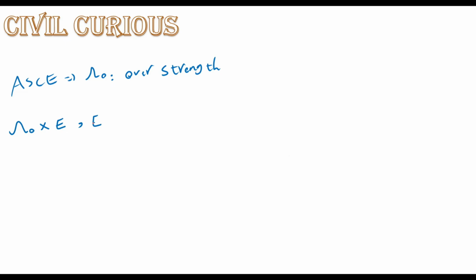Those earthquake loads include earthquake load in the x direction, positive and negative. Also, we have earthquake load in the y direction, positive and negative. You see, we are not going to make all those load combinations. We just scale our earthquake loads. Now let's do that in ETABS.